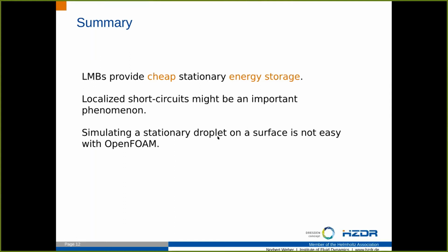The first question was about the use of a 90-degree contact angle as a boundary condition for the phase interface. How realistic is that for molten lithium on your surfaces? This depends not only on the lithium, but also on the impurities and on the shape of the metal foam. I think any contact angle would somehow be realistic, because we have so many dirty things in the battery. You never know how the wetting is. It changes from day to day. So we use 90 degrees because it's the most simple.